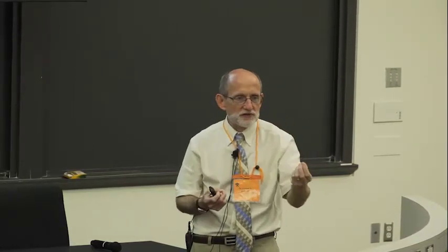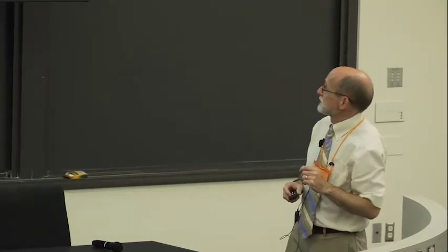I'm not worried about it anymore because I can get that reaction to occur between the solid phase carbon and the oxygen carrier. So it's a very nice finding early on as we started looking at this, that maybe I don't have to worry about coking so much. And frankly, I wish some of those guys who are doing FCC catalysts would put a metal oxide in there. Actually, I think some of them are, because it'll take care of their coking, right? I mean, just oxidize it. When they go out to take the oxide state, it'll reoxidize the metal.